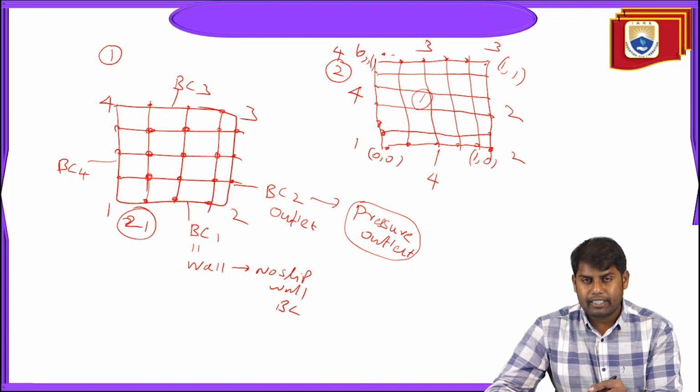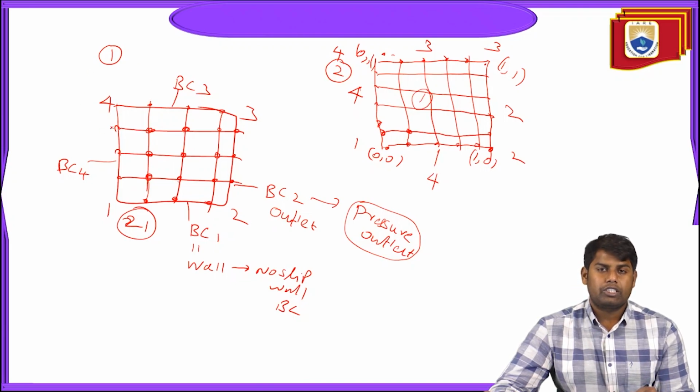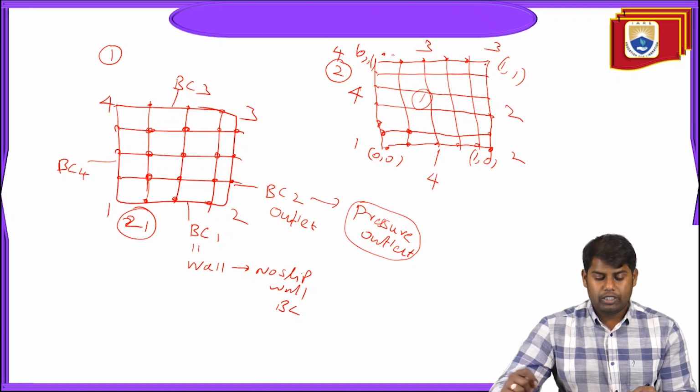The intersection of an x grid line and a y grid line will give us the grid point, which we have seen in figure 1. So this is the construction of the mesh, which started from coordinates, then lines, then creating the surface and the domain. Okay, so this is the procedure for how we create a mesh. A simple 2D mesh. Fine.